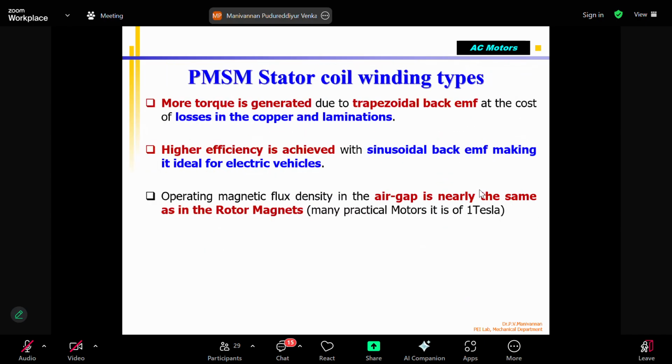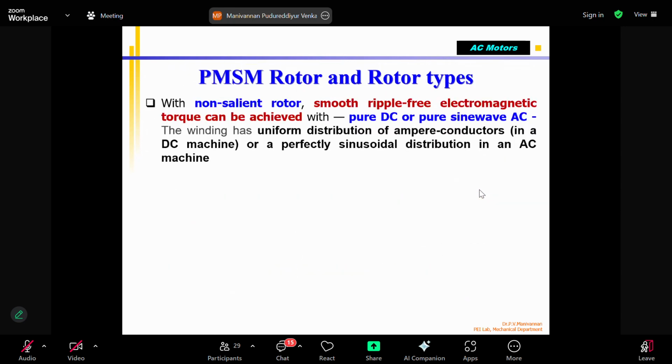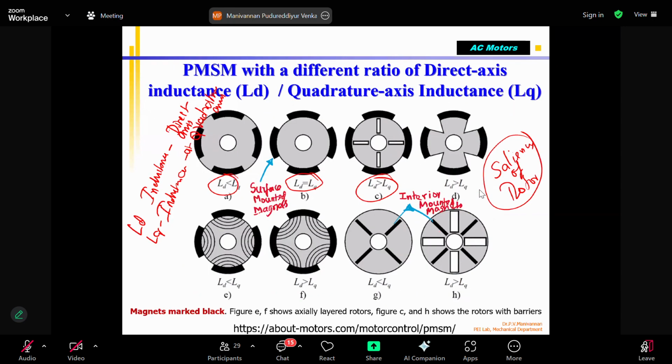Design torque production, smoothness, how much torque is produced in the permanent magnet synchronous motor. That's why they have different types of rotors. How are the magnets put over the rotor, fixed over the rotor? Please see that the magnets will be bolted, with screws and bolts, strongly, because this is going to rotate. It will generate centrifugal force, and the magnets must not come out.